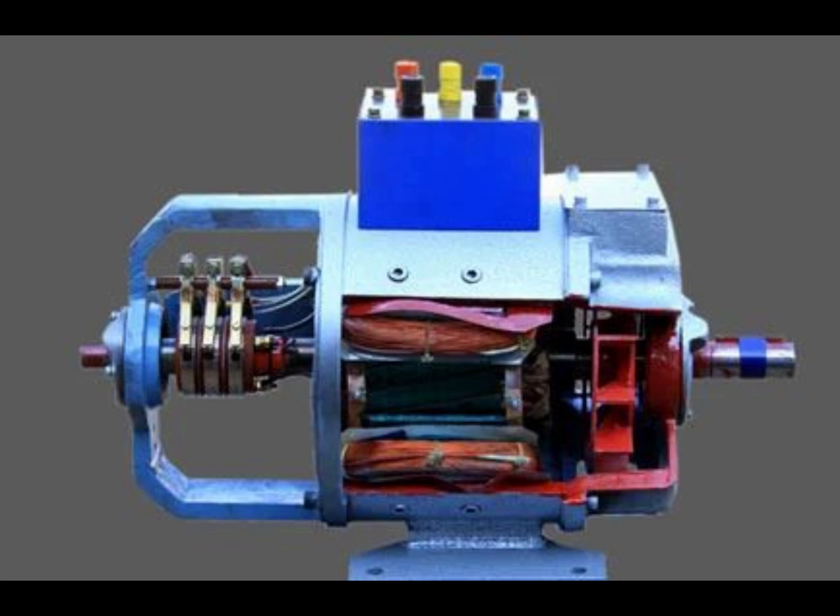The secondary resistance consists of banks of 3 uniform Y sections. Each section is to be connected to the slip rings of the motor. The wiring of the accelerating starters and the design of the resistor sections are meant for starting duty only. This type of controller cannot be used for speed regulation.